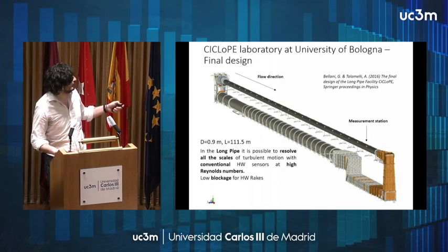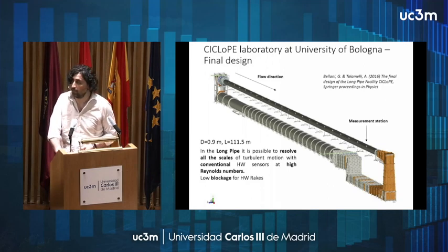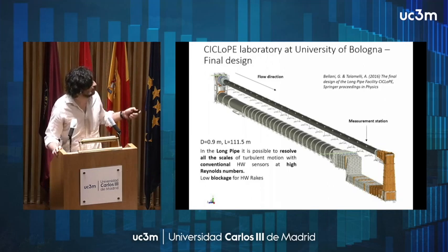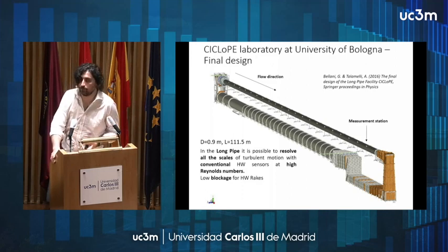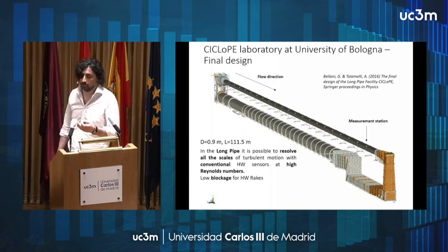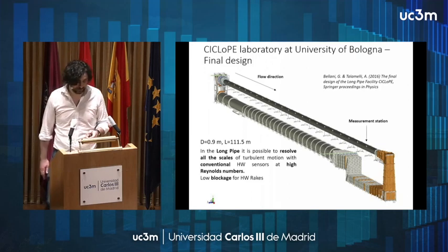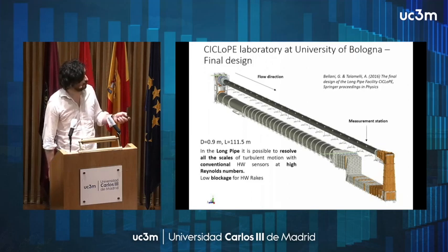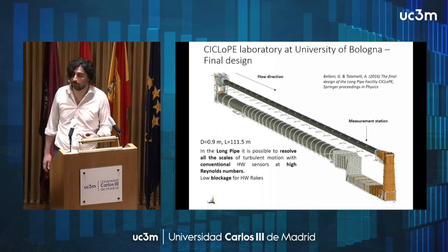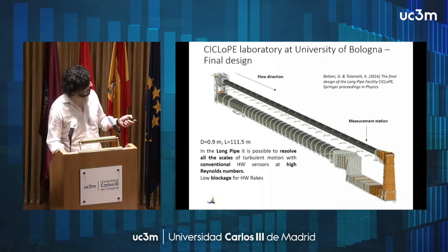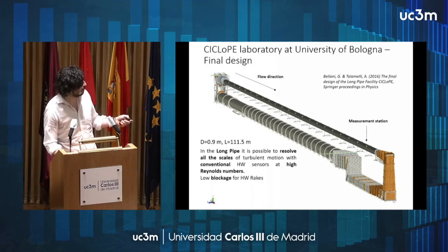So we have the two fans that are driving the flow, and we have all the features that originate laminar flow at the inlet, so that we have a natural development of the turbulence within the pipe. And of course, we have temperature control, because hot wires are calibrated at a standard temperature. And our measurements may last for hours. Stefano and Andrea may remember our long sessions of measurement in Ciclope, so they may last for hours and hours of measurements, the temperature must be kept constant so that our hot wire is also stable.